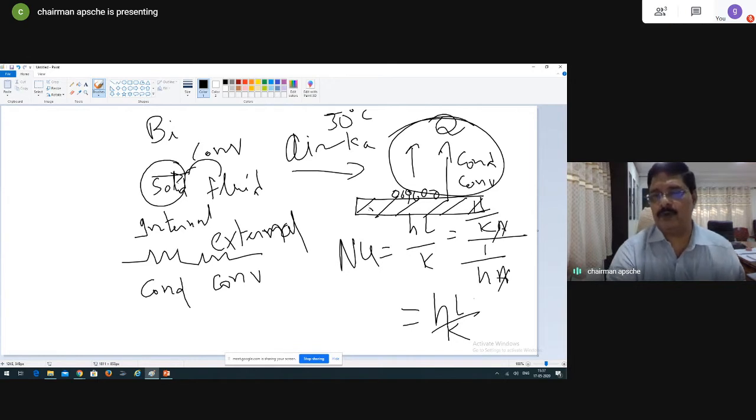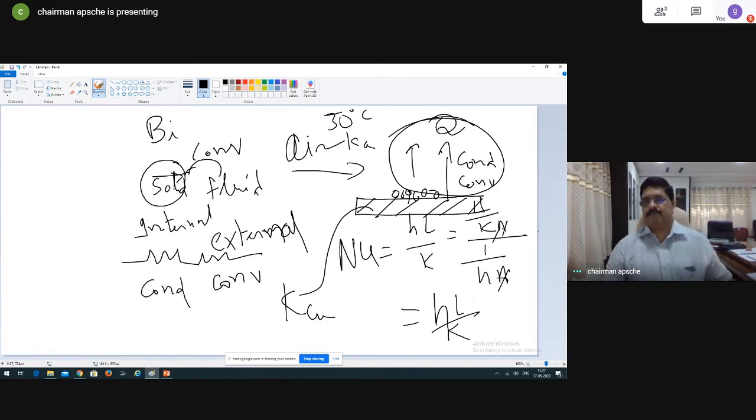It is flowing over, say, copper. He will also give the thermal conductivity of copper. Now, when you want to calculate Nusselt's number, the equation for you is hL by k.